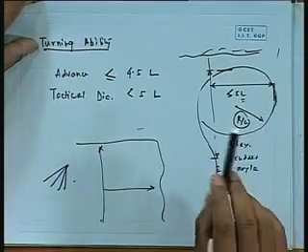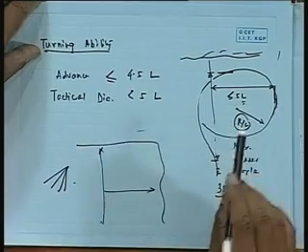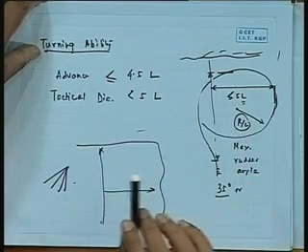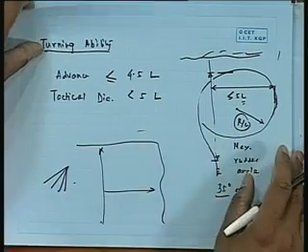I forgot to mention all these things will apply to both port and starboard rudder. Now you may ask why port and starboard rudder. The thing is that as far as rudder is concerned, port and starboard makes a slight difference for a single screw rudder, because in a single screw rudder the propeller moves in one direction, so the flow that comes to rudder may not be exactly along the x-axis, slightly angled. So there is a bias one side and other.